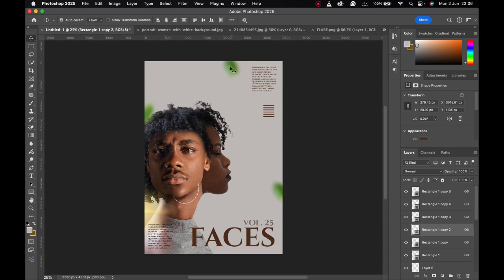Now the line I brought out is a very important one and can be used for demarcation of how you want all the elements to be aligned. To bring out that guide, you scroll out of your worksheet, come to the ruler itself, click on any part of it and drag it out. Then you are bringing a guide out. The line is called a guide. Where you have brought it out from is called the ruler. To reveal or hide your guide, you use Ctrl H.